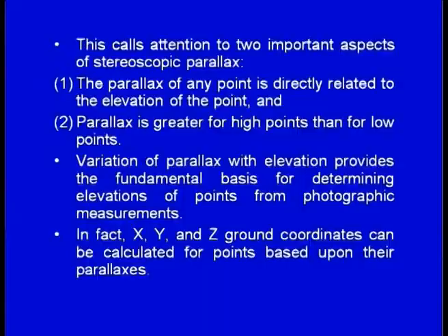So, this calls attention to two important aspects of stereoscopic parallax. Number 1, the parallax at any point is directly related to the elevation of the point, and number 2, parallax is greater for higher points than for lower points. Variation of parallax with elevation provides the fundamental basis for determining elevations of points from photographic measurements. The X, Y and Z ground coordinates can be calculated for points based upon their parallax.